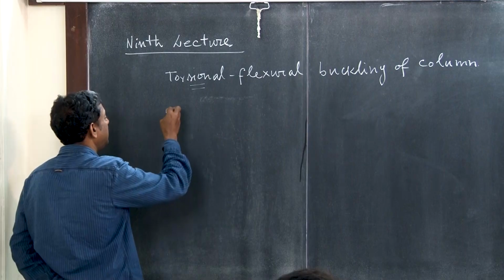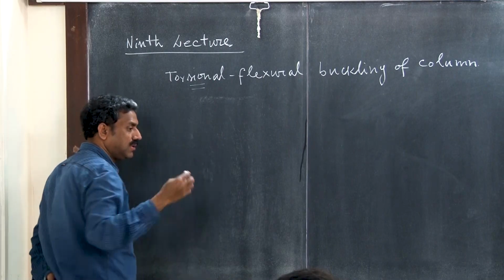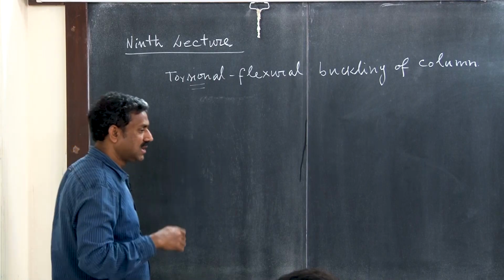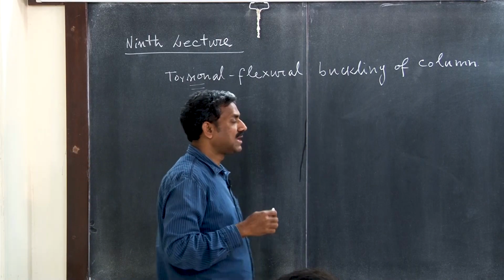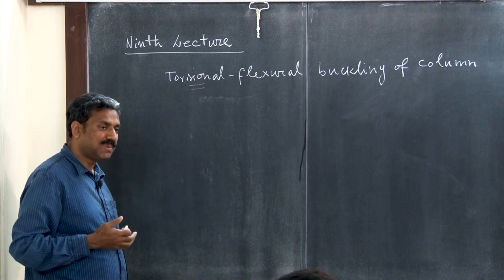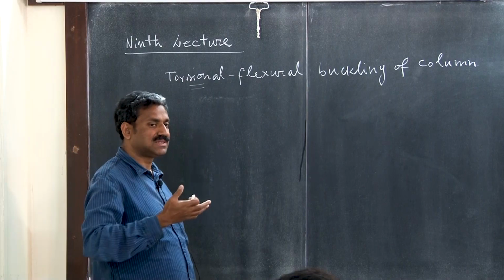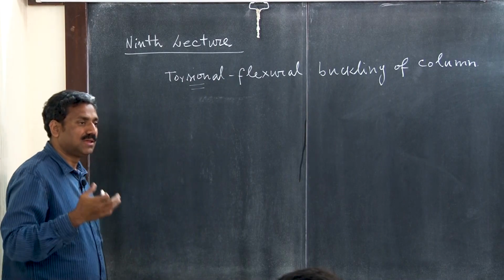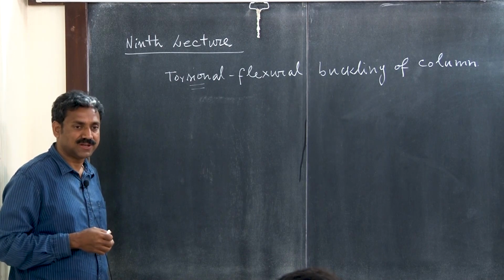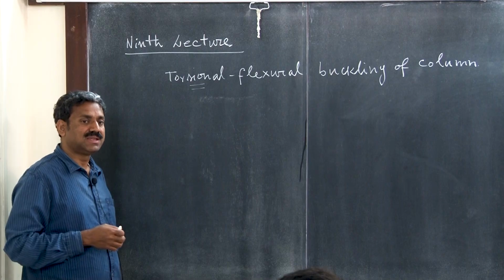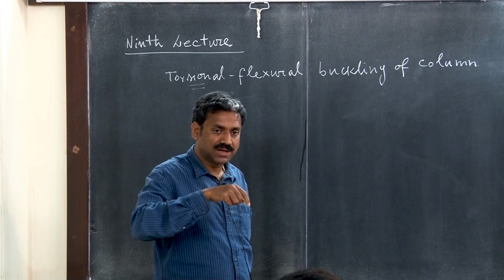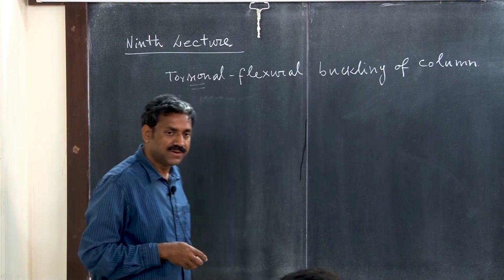We have learned about the torsion of circular cross sections, based on certain assumptions. The assumption for the circular section was that the plane section will remain plane, just like bending; here also, for a circular cross section shaft, the plane section will remain plane because there is no out of plane deformation. So, essentially the torque is resisted by the shear stresses, relative shear between the different sections, right.